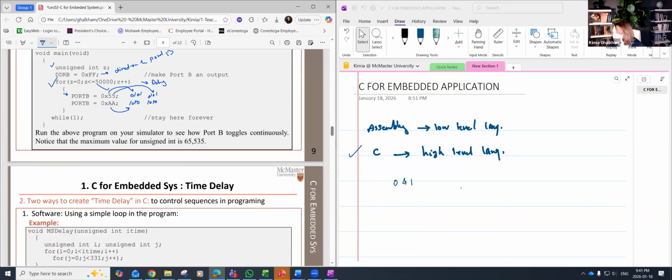in here just learn that the best practice to create a time delay is using hardware, not software. The way that I do it right in here might actually be functional, but it's not the most accurate method. Usually we create delay through hardware, not through software, since there is a timer register in the microcontroller that we can assign to do the delay for us.